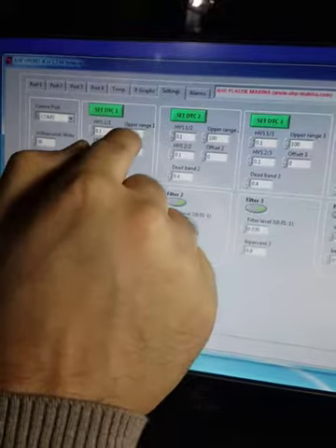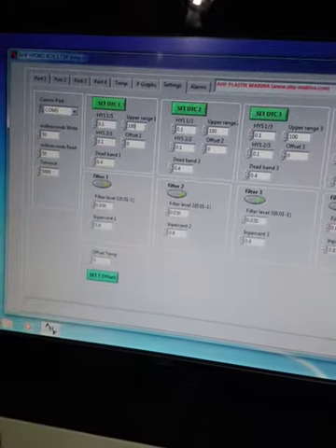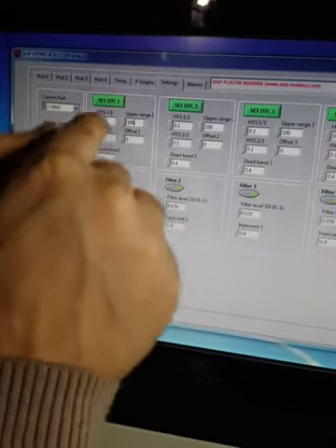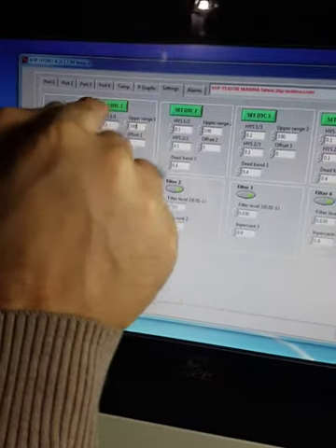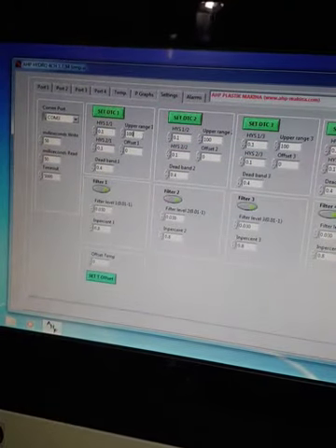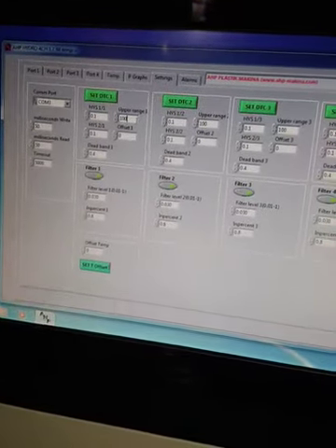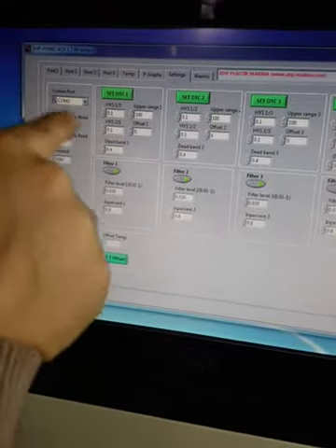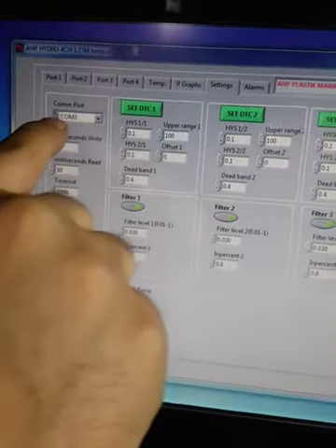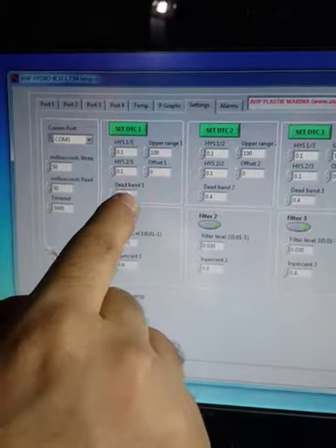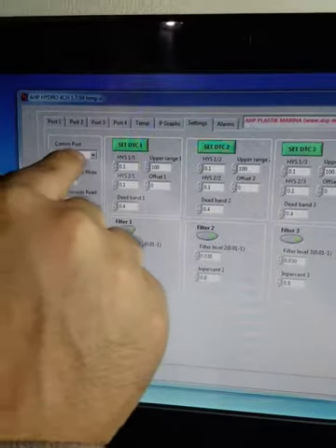After setting the upper range of the sensor that you have used, you will need to push the set DTC1 button. It will be adjusted in the CPU, in the memory of that controller for that specific line. Here you have a connection. The main parameter in this page the operator needs to know about is the communication port.